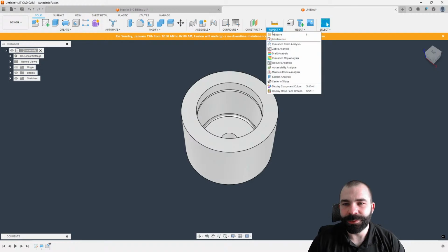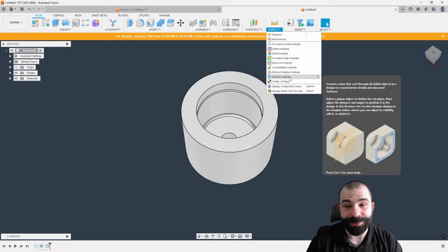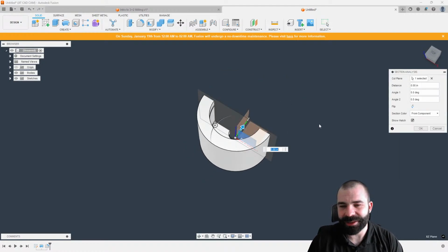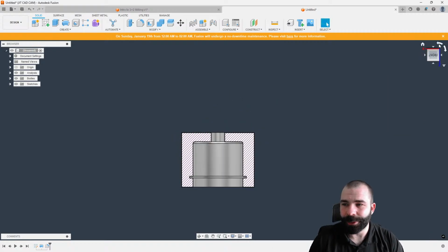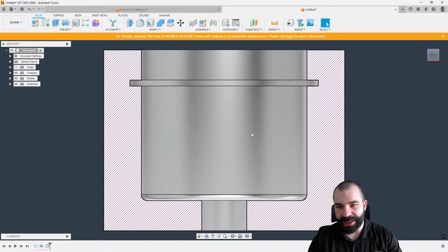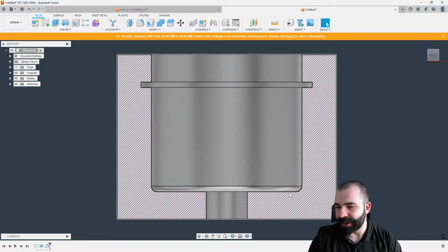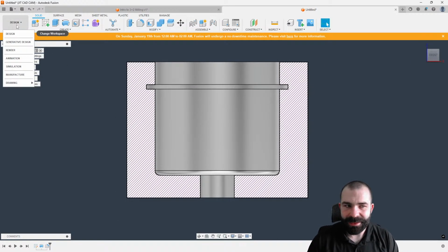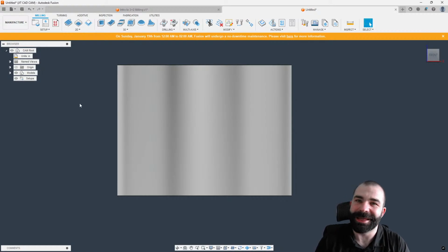And then let's do, again, pro tip here, guys. You could do a section analysis, but do you want to see something that I complain about, but I understand? When I say section analysis on the design side of the software, and I switch over to CAM here, if I can ever orient my model, right? Travis, let me know in chat. That's what you're talking about. You cut this actual O-ring groove, and then you were talking about wanting to blend down here at the bottom, right? I did my section analysis in design, but when I jump back to manufacture, I don't have an option to use that analyze. So as you're seeing, I have to recreate that section view on my part.